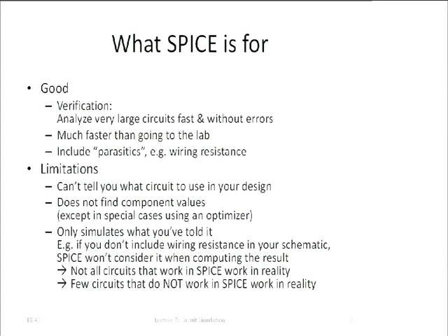And consequently, even though you've checked the circuit with the simulator and in the simulator it works just fine, that does not always mean that it will work in practice. So sometimes you simulate, it worked fine in SPICE, you go to the lab, you build it everything right, all the wires in the right place, but because there's some differences between what you told the simulator your circuit is like and what your circuit really is, for example, the resistors are all a few percent smaller than the values that you put in, because, you know, if you buy resistors, they're not going to be precisely dead on, right? Then it may not work in practice. So not all circuits that work in SPICE work in reality.